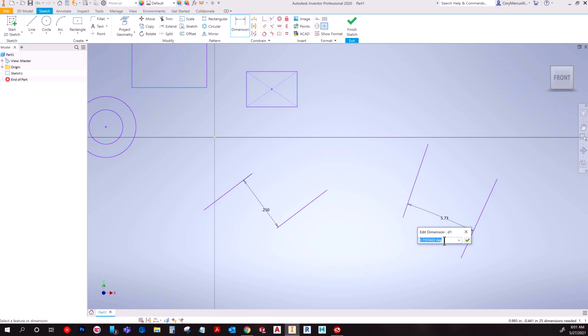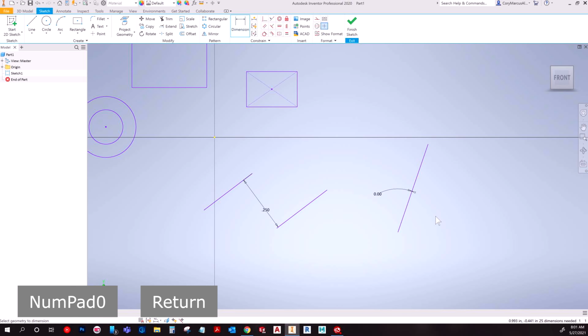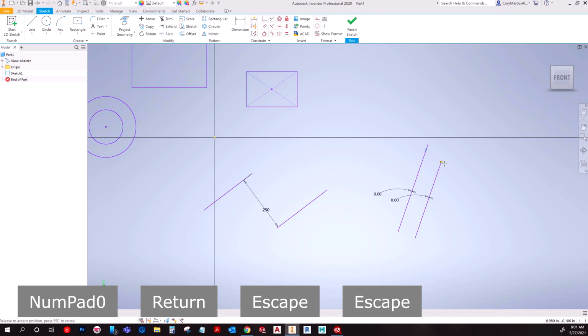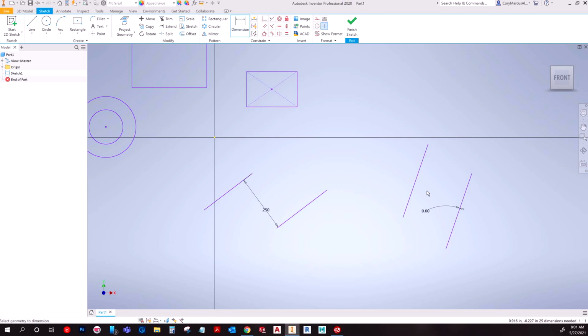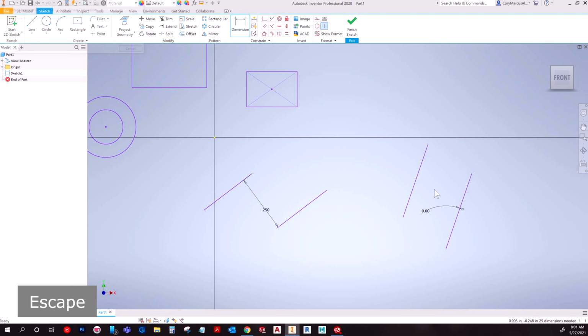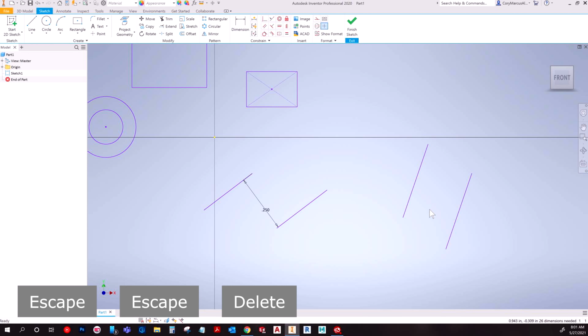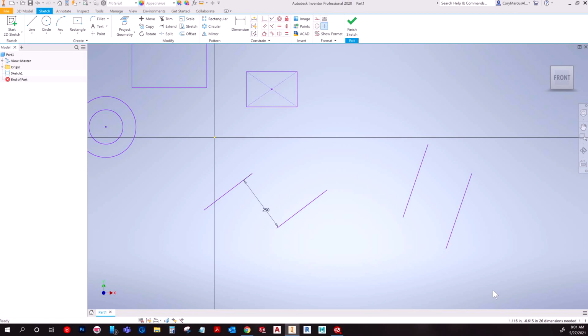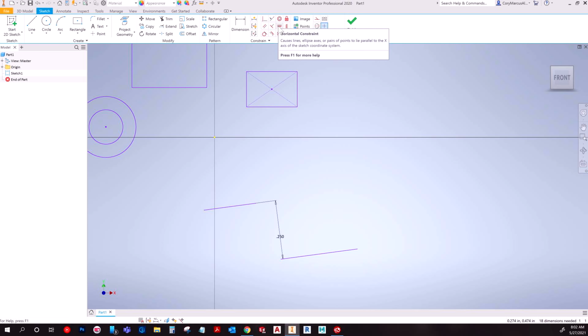I screwed up. Now technically, I guess, yeah, you could type in 0 and then pull them apart and then you could put an aligned dimension, but that's just bad drafting. And see, it doesn't even let you actually. So basically, if you're working with angles, the way to position lines to where you can actually dimension between them is it's gonna be parallel. And then obviously when it's parallel, you can still reposition things. You're just working with angles. It's pretty straightforward.